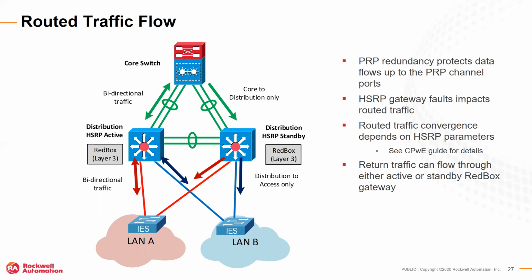And then outside of that architecture, you could have things like your data centers or your HMI system or some of your data systems, which could survive. What I'm talking about here is at most 3 seconds or so of a convergence time. So your control and IO can't survive that. They need to reside inside of your PRP network, along with other things like drives.